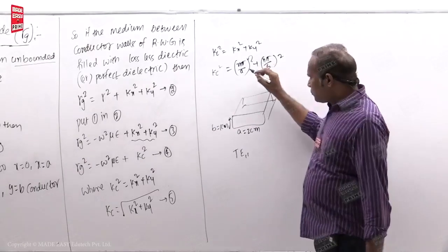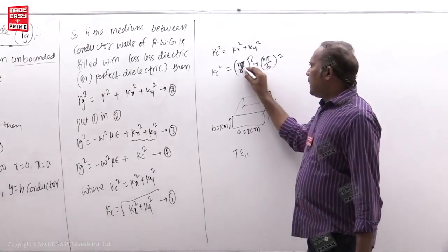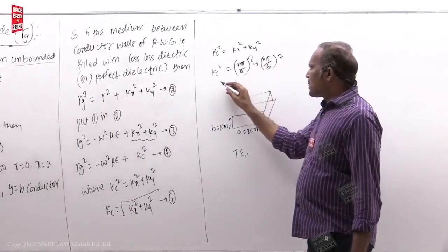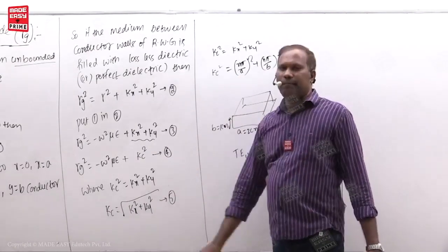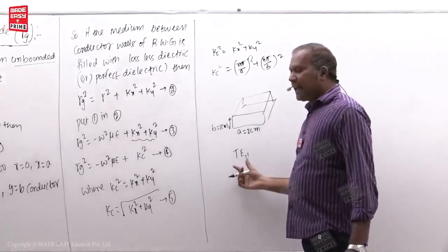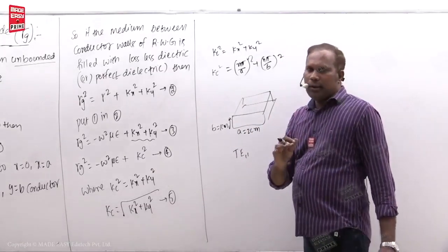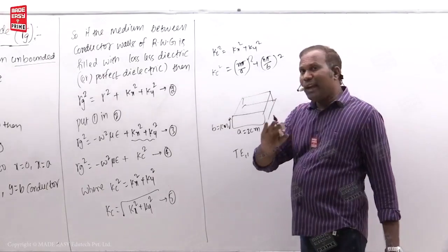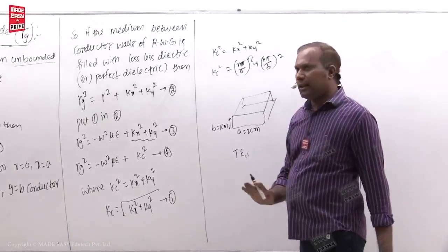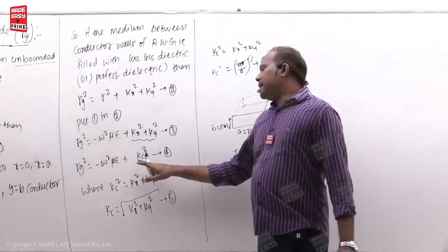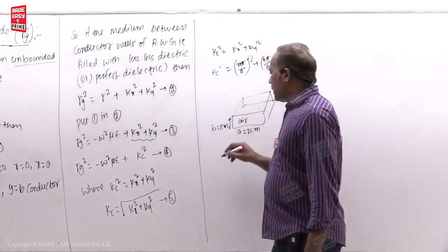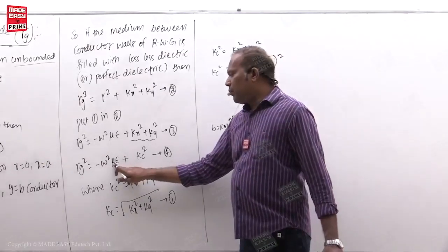So then automatically the m value is constant, the n value is constant, a, b constant, pi also constant, kc is constant, student. Once you select the rectangular waveguide, then you will be sending energy through a particular mode. Mode means the way you carry the energy, or otherwise the way you carry the power. Later on we will see that. Then kc is constant, student. Then if you select the air medium, then epsilon is equal to epsilon naught, mu is equal to mu naught.